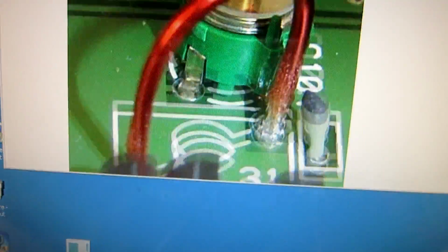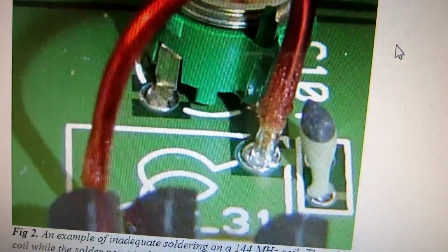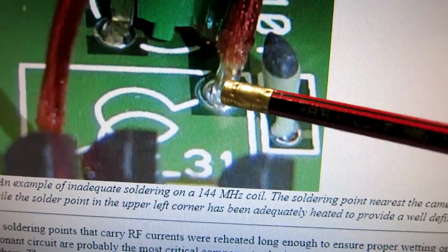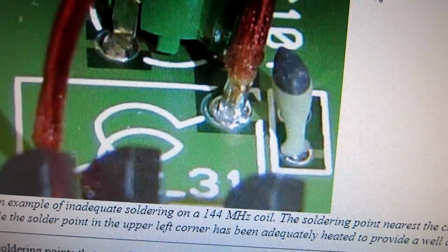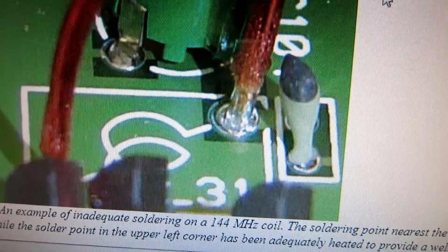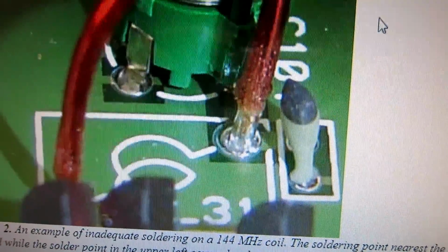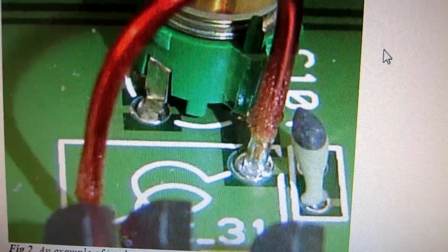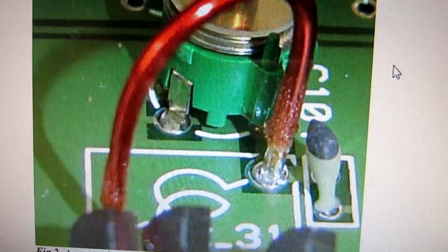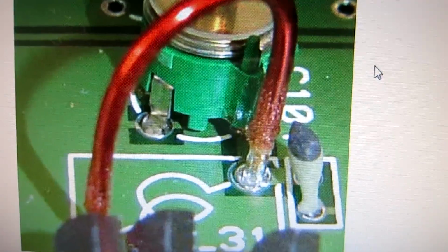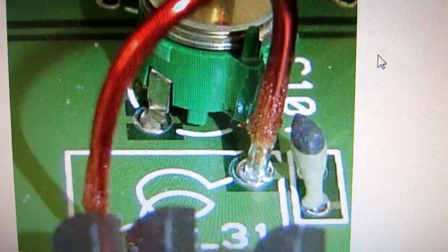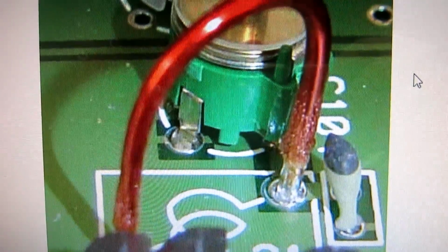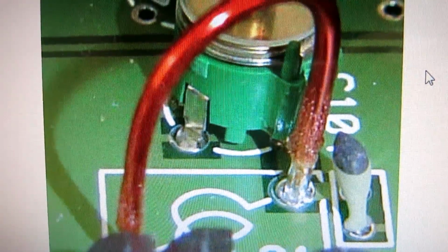The important thing is here. Here is a poor soldering, and that results in noise modulation, amplitude modulation sidebands. And at levels close to the level we see here, maybe not quite as strong, but anyway strong enough to be a problem for this receiver.